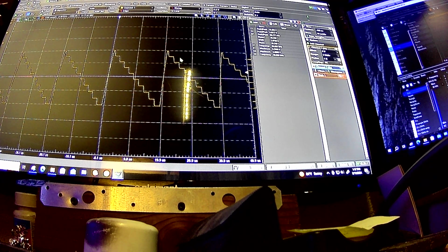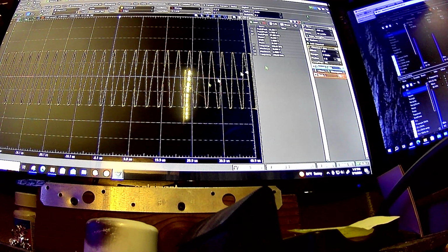Generally speaking, if you filter at about 500 kilohertz, no less than that, although you might be able to get away with less, you're probably not going to generate a very fast transition like what I showed you on that other screen very often. You're probably not going to do this very often, right?